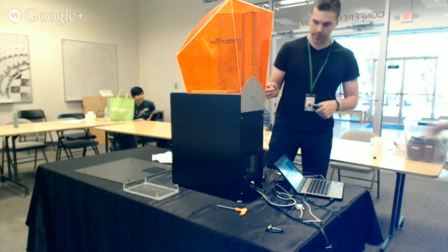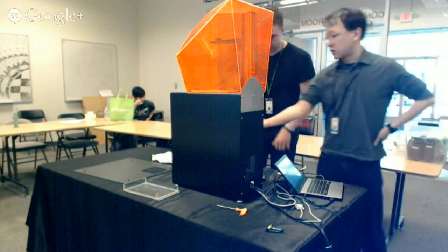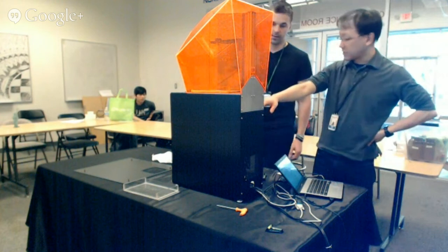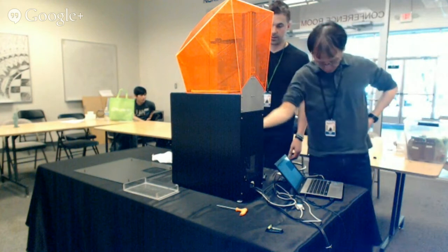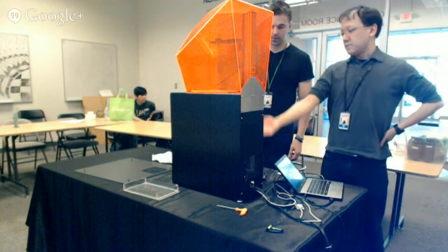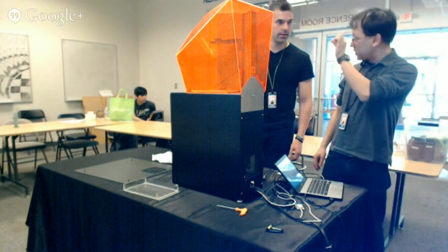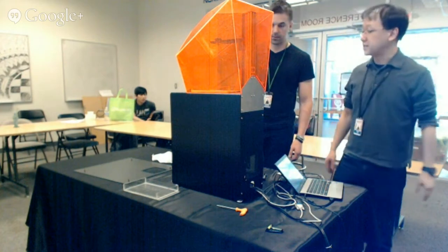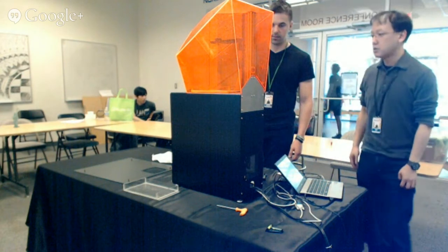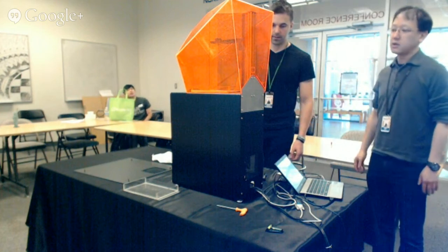Yeah, I mean, this thing is on a bracket. This bracket is designed to be moved, right? The thing is that the calibration sizing changes whenever you move this thing. So there's a procedure every time you want to change your resolution, and that's what you're really doing. When you're moving it closer, you are increasing the resolution, in that you get smaller and smaller dots, and that also increases the intensity. And then further away, bigger dots, less intensity, longer exposures. But whenever you do that, you need to recalibrate.